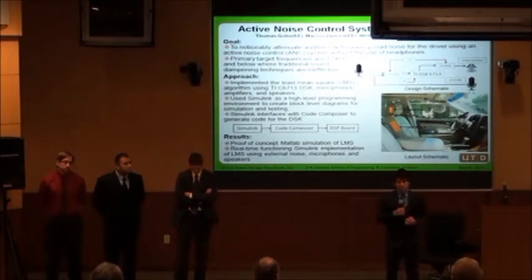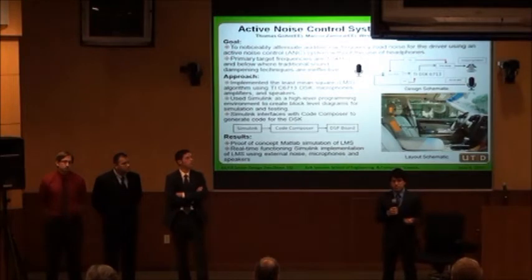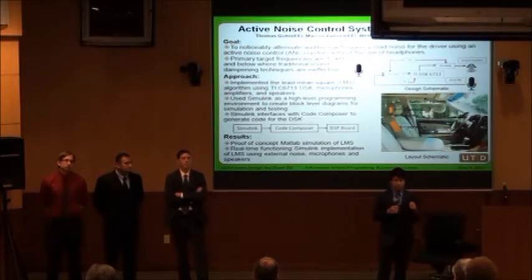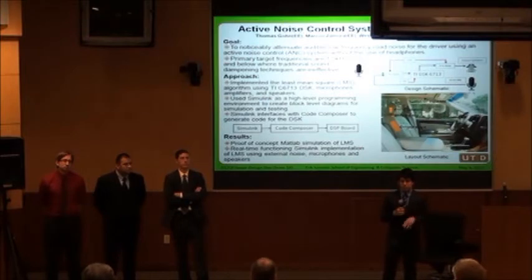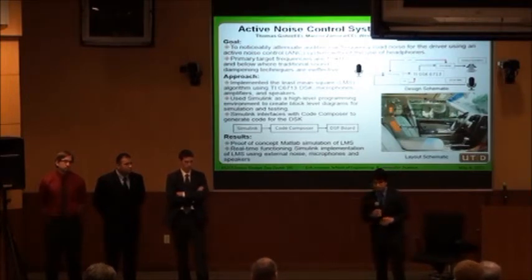Now, first semester, we focused on getting familiar with the DSK and figuring out what algorithms we were going to use, and we made simple filters in C++ using Code Composer. This semester, we focused on implementing the LMS algorithm onto the DSK, and we also moved from Code Composer to Simulink, because it allowed us to implement our hardware and test it without the board itself, and also put our code on the board.